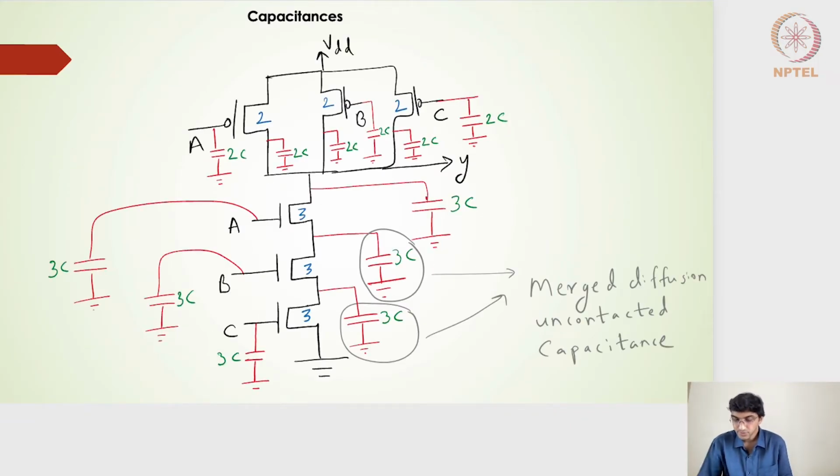Moving ahead, so if I have this particular scaling on each of these transistors, we need to understand what the capacitances associated with each of these transistors are, right? There are three capacitances: the gate capacitances, the depletion capacitances, or the diffusion capacitances. Put together, I have detailed it out. I have arranged all the capacitances except this non-switching capacitance, right? Non-switching capacitance is this capacitance.